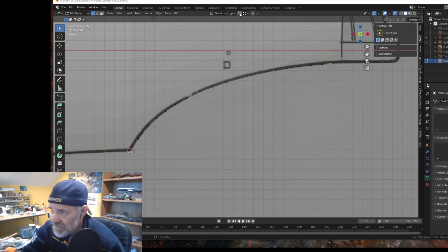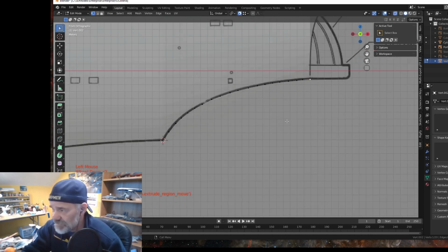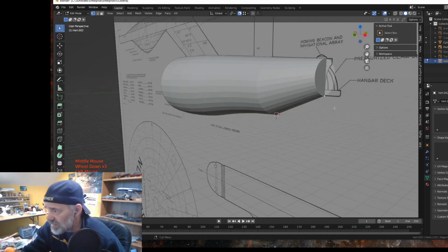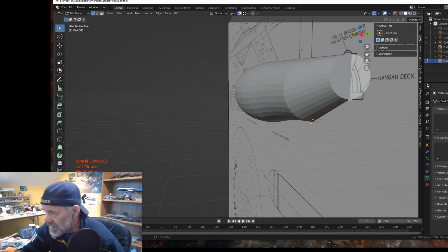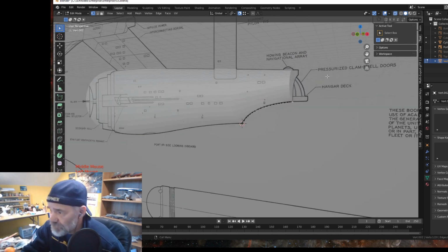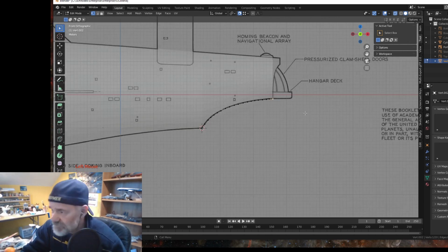So I'm going to turn snap on. Okay, and I'm going to extrude and snap to that vertice that's on that end piece. Okay, so I hit enter. I mean, I don't hit enter, I just click. Now if we zoom out and let's get out of ghost mode, it snapped to this corresponding vertice on our end circle, right? Okay, so let's go back to ghost, tilde F to side view.